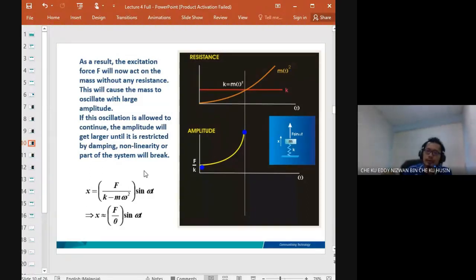So that's why in industry, when your system is running at resonant frequency, then you face very high vibrations, and there is a high potential for the system to fail. So it's a high likelihood to fail, as they call it in the industry. From this point to this point, you can see that it keeps increasing because the resistance keeps reducing.